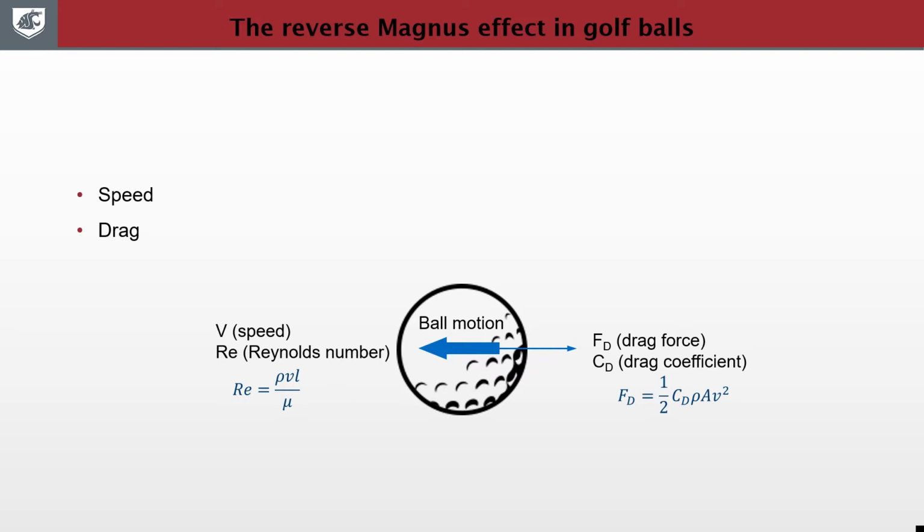It is normalized by a drag coefficient. If the ball has backspin, a lift force acts normal to the ball path, giving it extra distance. It is normalized by the lift coefficient, as was done for the drag force. It was first observed in 1852 by Heinrich Magnus, which is why we refer to lift as the Magnus effect.